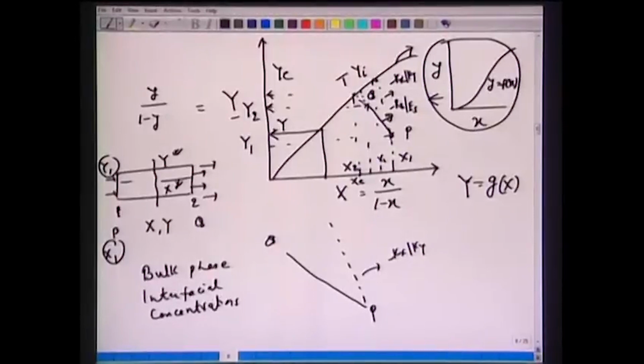Interfacial concentration. So these two phases we can mark to obtain the driving force for mass transfer, yi minus y. With these two curves, the operating curve, which is linear here, and the equilibrium curve y-x, now we have all the mole fractions of y and x between these points P and Q and this equilibrium curve. Physically, all it means is that we have an interface of the two phases.